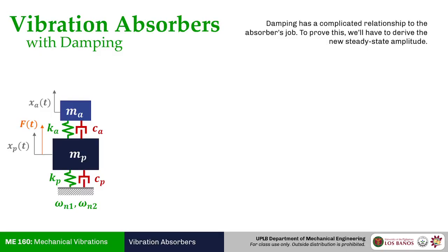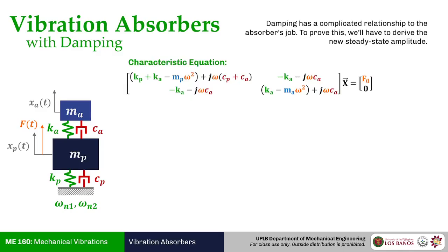Because if you go to our chapter 6 module again for degrees of freedom systems, you notice we completely skip the damped 2DOF system. And there is a good reason for it, because if you take the impedance matrix of that, you get an imaginary term from the damping expression itself.